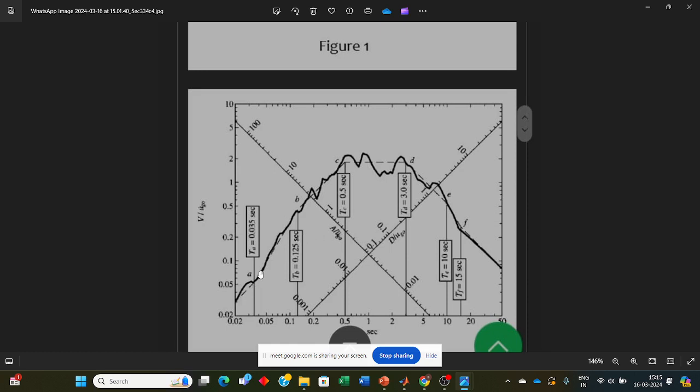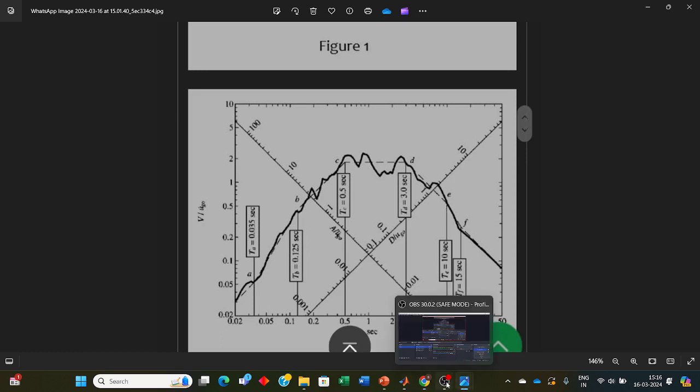And we can see that here, if you extend this line, it will cut this axis at 1. This means that this plot is for U ground double dot 1g, but you want the value for 0.5g. So basically all the values will be scaled by 0.5g. So I hope this is clear.